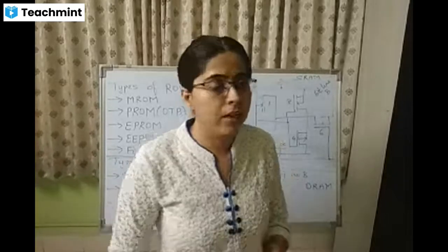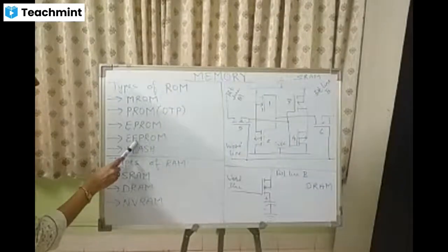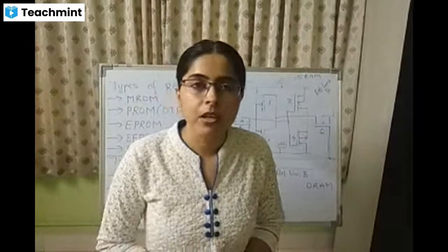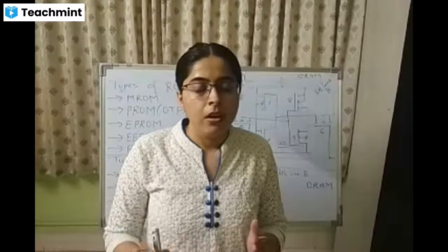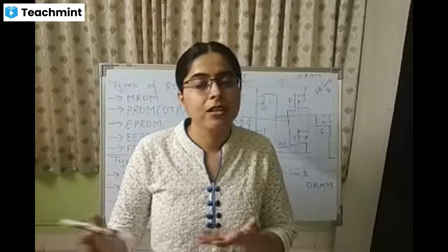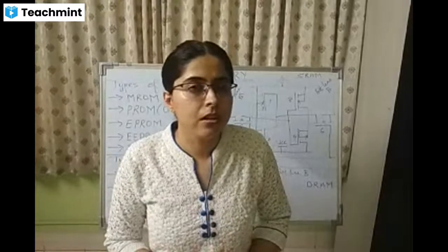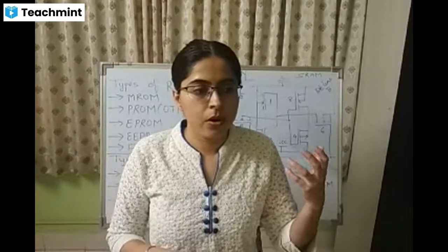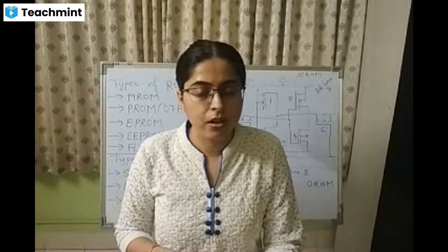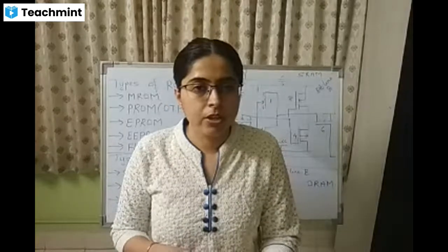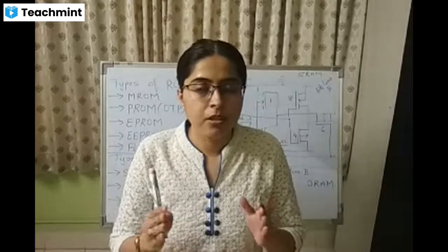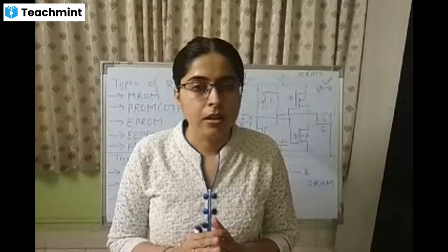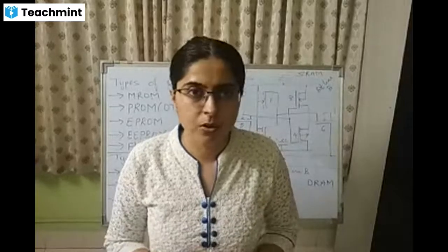So there is a further advancement, that is electrically erasable programmable read-only memory. What do we mean by electrically erasable programmable read-only memory? The contents of the memory are alterable by electrical signals. Electrical signals are used to alter the contents of the memory. I mean to say, suppose you want to remove the contents, so you put the chip in the erase mode. When the chip is in the erase mode, electrical signals automatically alter the contents, the previous program is erased, and you can reprogram the chip.